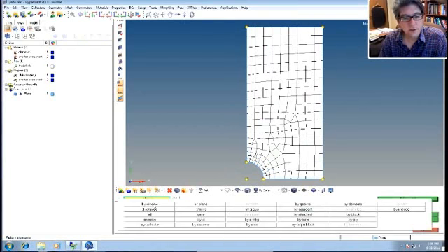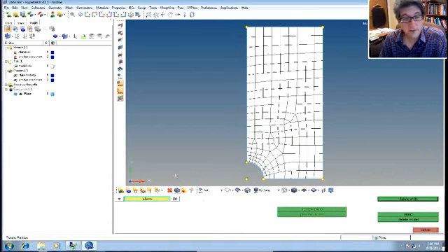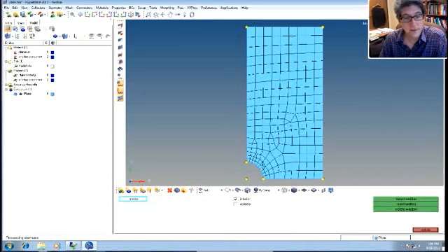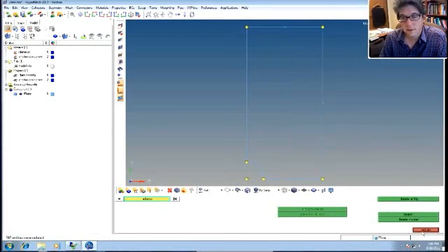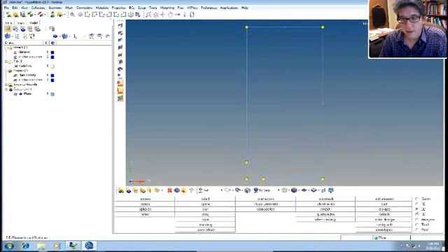Other useful ones, you can select by window, you can select by collector, right? So if you want to do a select by window, like let's clear it, select by window, you could pick the points that define the selection window. And you can see there we did that, and it selects all of them. So it's the same difference, okay? Then we delete them. And there it goes. No more elements. Okay, let's go back to 2D and regenerate it with planes.